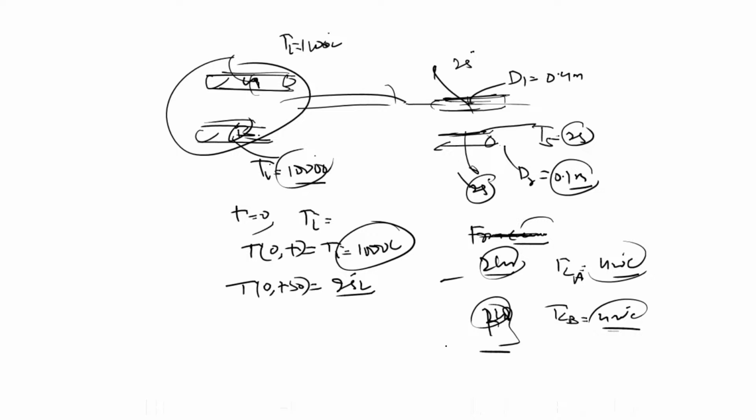Question is clear. LC is the characteristic length, I told you in the last lecture, where the maximum temperature difference that we can expect is from center to surface. And this is the LC. LC is called the radius. You should not bother about eta here: it is x upon under root 4 alpha t, and x is nothing but LC. LC is the characteristic length you should write here. Clear?